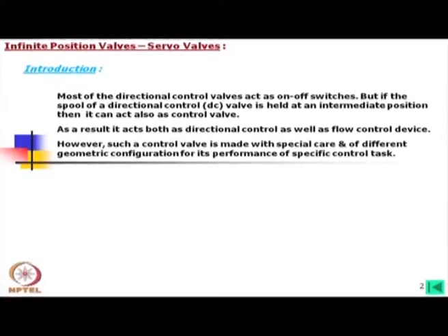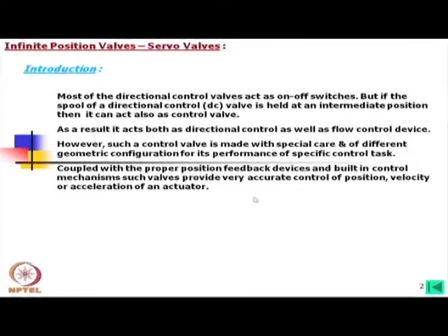However, such a control valve is made with special care and of different geometric configuration for its performance of a specific control task. Coupled with the proper position feedback devices and built-in control mechanism, such valves provide very accurate control of position, velocity or acceleration of an actuator.